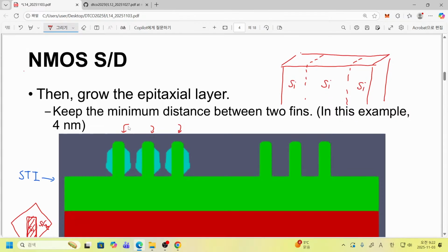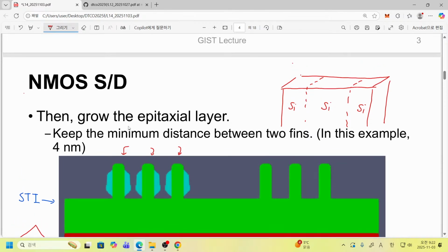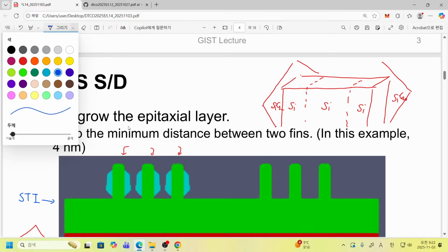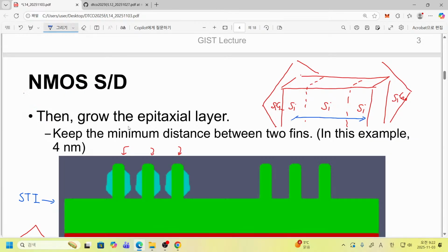And if we have, for example, silicon germanium here and silicon germanium here, the important direction is this channel direction, and from the viewpoint of this silicon, it is just surrounded by silicon and has no real compressive stress applied to this silicon channel.